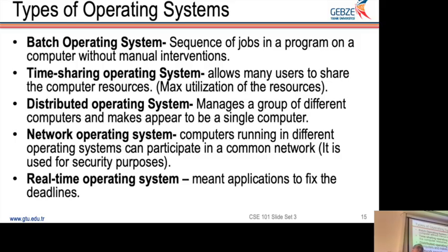Today's ignition systems and injection systems are electronic and controlled by the engine control unit. In the older days, what did we have? We did have carburetors, right? Carburetors are mechanical devices which mix air and fuel with a predetermined ratio, and there are some vacuum connections to it. So it's all mechanical, and it is basically a spray. It is spraying fuel into air. We assume that it is mixed and it is burned in the engine.